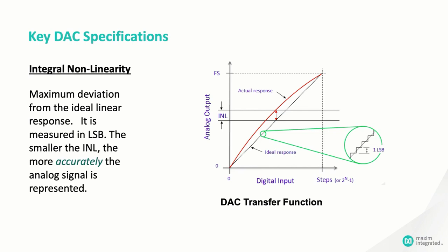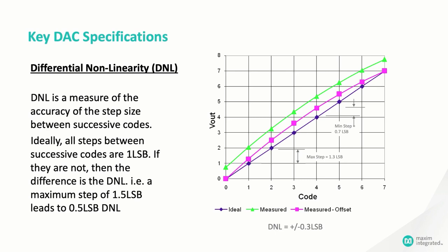Here's the main idea. Remember the difference between accuracy and precision? Well, INL is one measure of the accuracy of the converter, but what factors affect the precision? Well, we talked about one factor that dictates precision. That's the resolution. But other elements can affect precision too. What if the individual steps average to a straight line, but each step varies slightly from its neighbors? Well, that kind of imprecision is called differential nonlinearity. Part of the reason differential nonlinearity can be an issue is just the binary nature of the input.